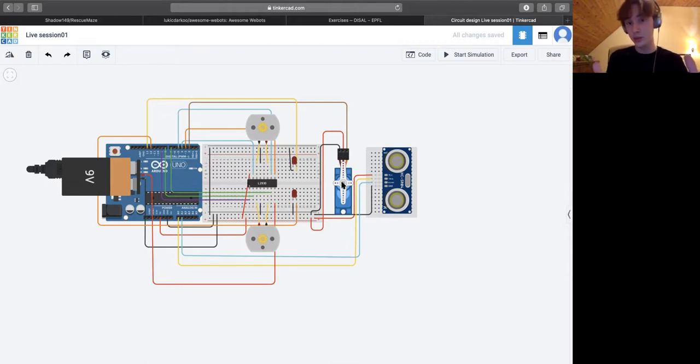We're going to use my servo right, about 30 degrees function, and then we want to turn our servo to the right. As we turn to both of these angles, we want to measure our distance and then choose the direction with the largest distance.